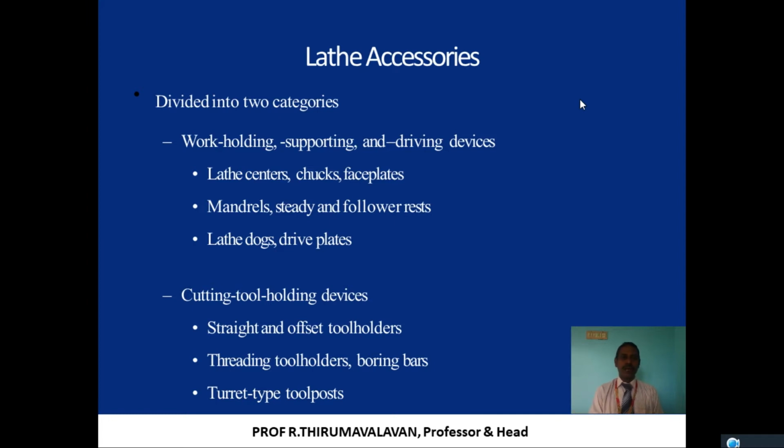Work holding devices are used for supporting and driving the work. In this category come lathe centers, chucks, faceplate, mandrels, steady and follow rest, lathe dogs, and drive plates. For the cutting tool holders, there are straight and offset tool holders, threading tool holders, boring bars, and turret tool post. We already saw the turret tool post in the turret lathe machine, where there may be 6 tools held on the turret. We will see them one by one.